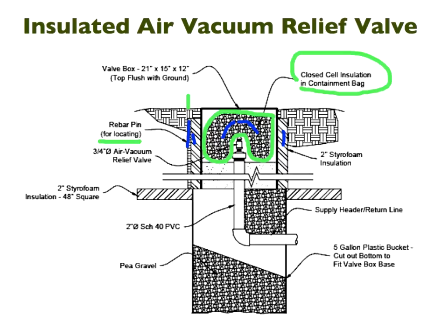Under real tough conditions, which a lot of you have, it's a good idea to put a 5-gallon plastic bucket. This is the container for the air vacuum relief valve, with a valve box with a cover. But underneath that, dig down, put a 5-gallon drum in there and put pea gravel underneath and take this below the freezing.